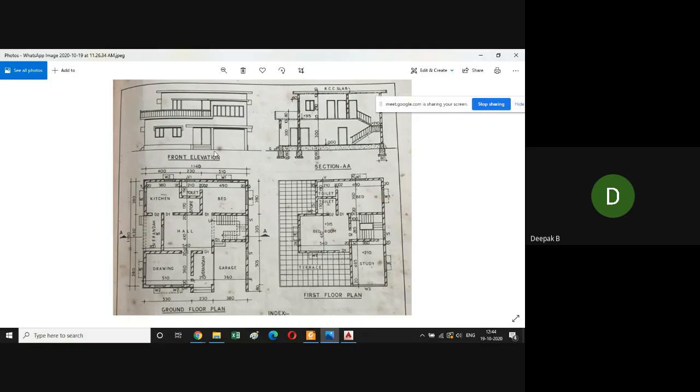And actually you should have also drawn the stairs here. And the step, there is also a door. If it is not closed, you should be drawing that also here, but it is not available in this particular drawing. That is wrong. You should draw the opening of door D1 and 2 sets of stairs here to show that you have an opportunity to climb up those 2 stairs into the space here right next to the hall. So make use of both these images so that you are incorporating all the details.